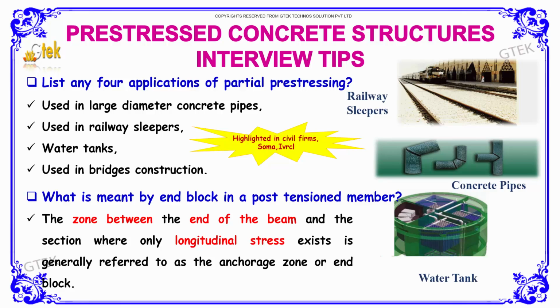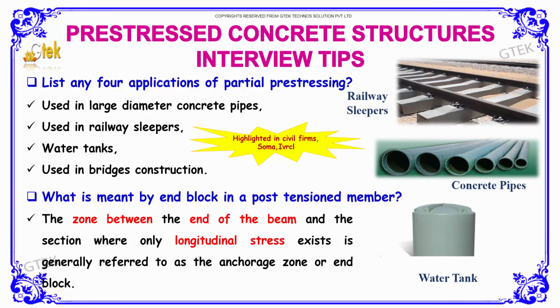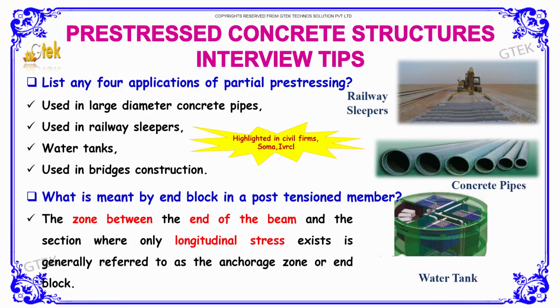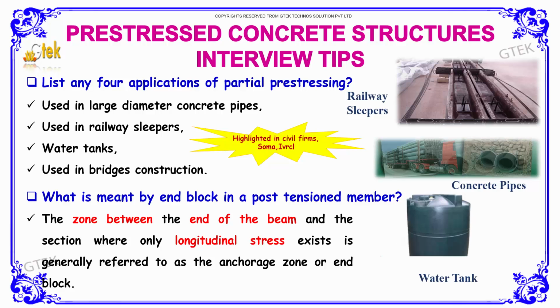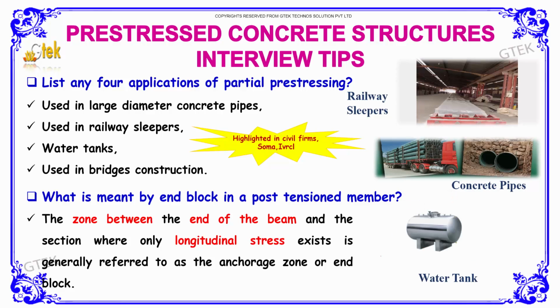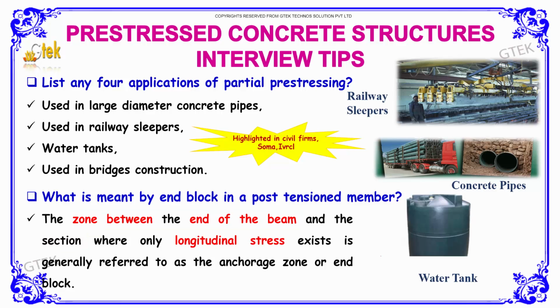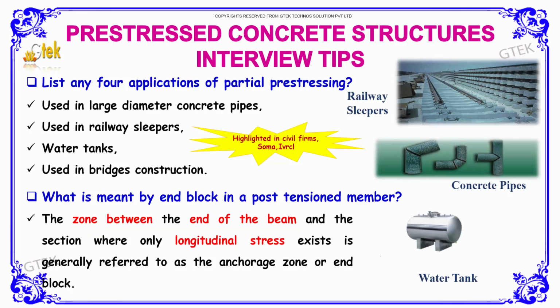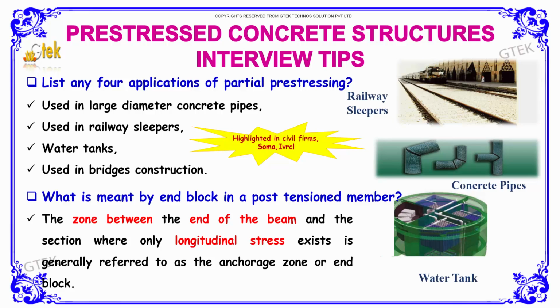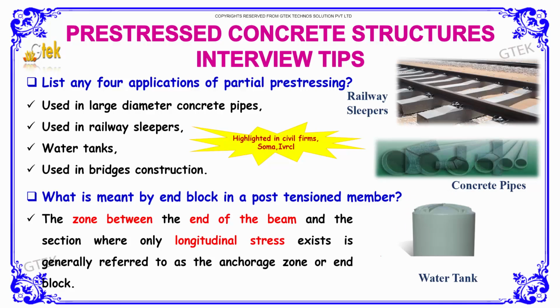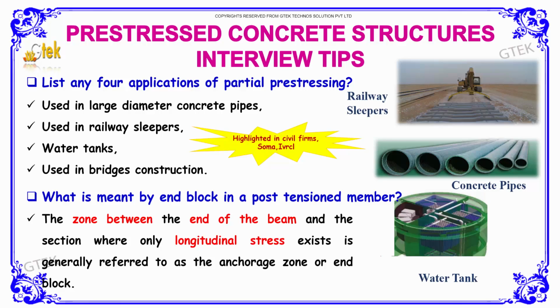Let's move to the next question as follows. What is meant by end block in a post-tensioned member? The end block in a post-tensioned member is a zone between the end of the beam and the section where only the longitudinal stress exists, which is generally referred to as the anchorage zone, or else we can call it the end block.